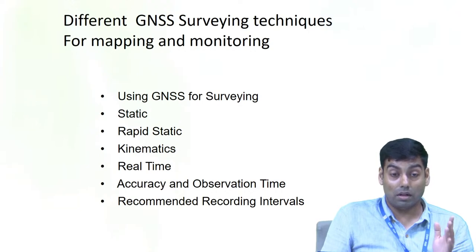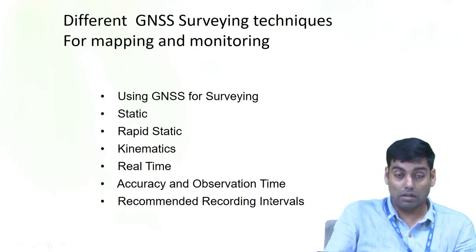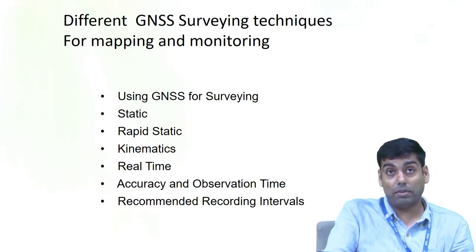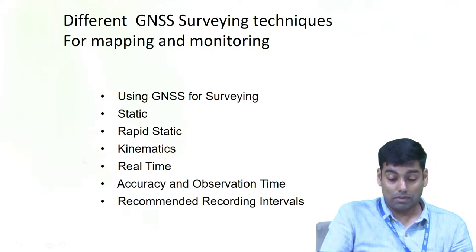So depending on your storage and so on, you define the 1-second sampling interval to acquire the GNSS signal in your receiver. And normally for static measurement we fix 15 seconds, 30 seconds, because this is the minimum requirement. With the help of that you can get a very good volume of data, and you can resolve all these ambiguities.